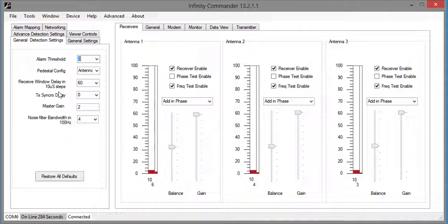If you try and look for a tag signal too quickly, instead of seeing a tag signal, you'll actually see the back end or the ring down in the transmitter circuit itself. So if you look for that tag too quickly, you'll actually see the transmitter rather than the tag. So we have to put a delay in following the transmitter before we start to look for the tag, and this control sets how long that delay is.